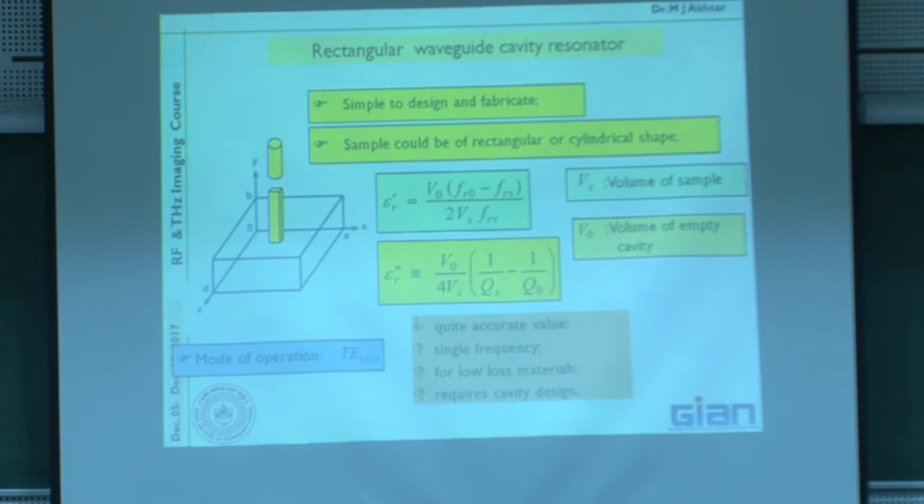Now, what has this to do with imaging and how does it help? So this was the conventional thing. Now here, if I want to design a cavity, let's say at 10 gigahertz, what are the main considerations that you have to see? For example, the length of the cavity. What should be the length of the cavity in terms of wavelength? You have done rectangular waveguide, you have done cavity. So if I convert a waveguide to a cavity, what should be the length? Let's say if I want to design it for the lowest order mode, half wavelength, right? So if it's X band, 10 gigahertz, it is lambda by 2. That means the size of the resonator will depend upon the wavelength, right? And it's the same thing as in imaging, where we say image size will depend upon the wavelength. So something similar.